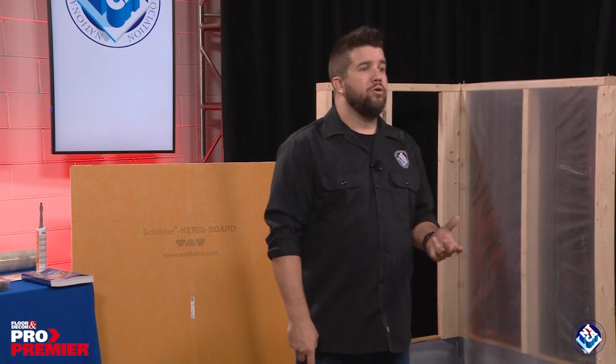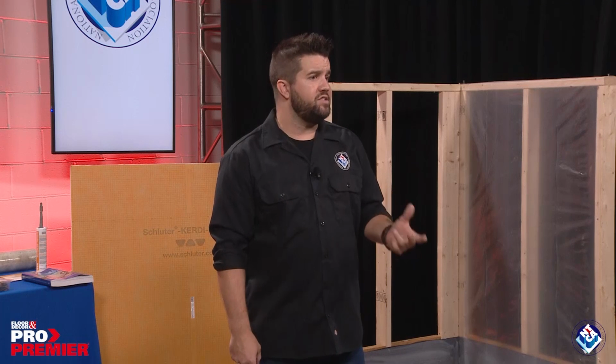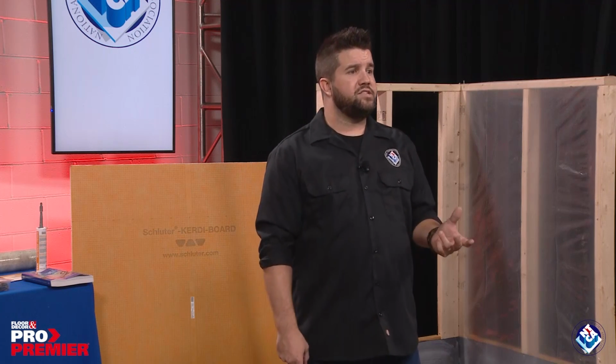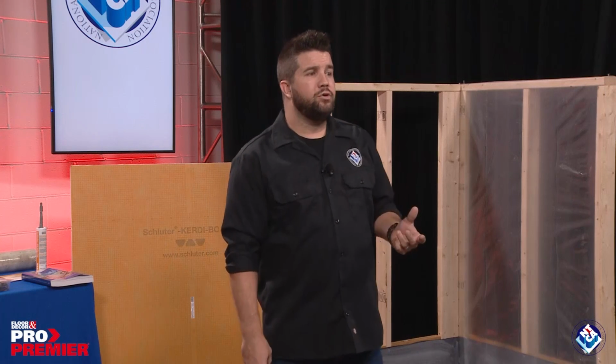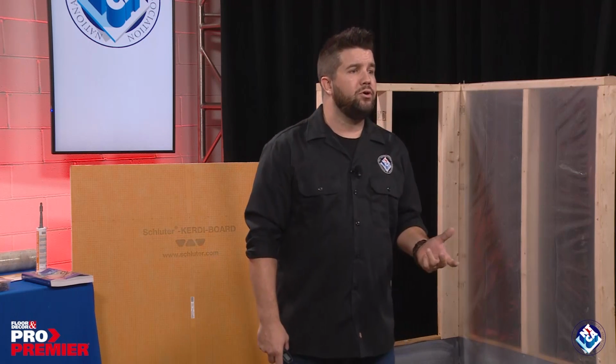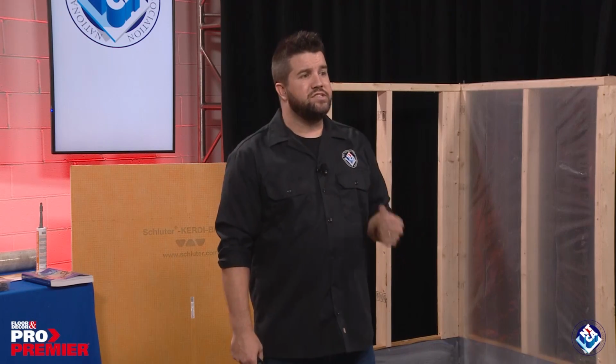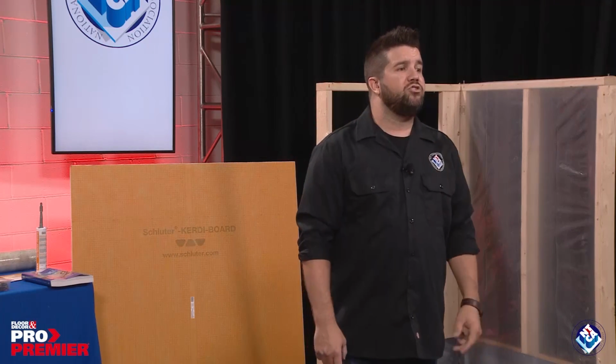When choosing a backer board for your project, you can generally find a TCNA handbook method that lists an ANSI test method or an ASTM standard, but it's also important to remember to check with your local building codes for approval of these specific backer boards in the application you're designing.